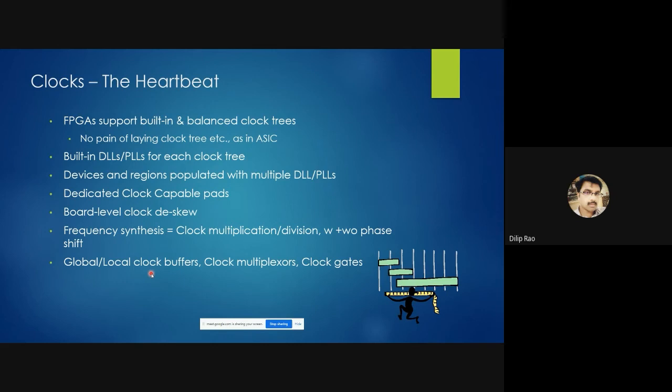There will obviously be high fan out, and that is going to impact the clock waveform adversely. To avoid that, the FPGA tool intelligently inserts clock buffers in the clock path, so that high fan out is taken care of. You don't really have a case where one single line is feeding some 500 loads. That will never happen. It will have intelligently placed clock buffers where one line is duplicated, and for feeding 500 loads, we have say 10 or 20 or 30 identical clock lines feeding those loads. That is the meaning of clock buffers.